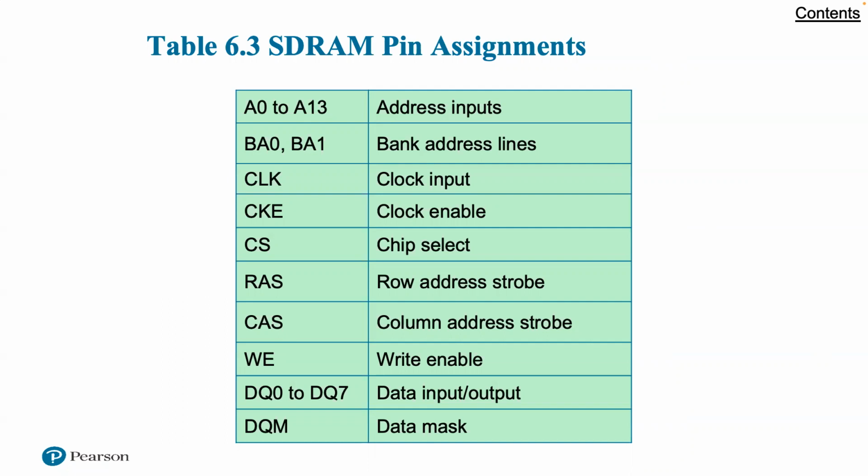The SDRAM employs a burst mode to eliminate the address setup time and row and column line precharge time after the first access. In burst mode, a series of data bits can be clocked out rapidly after the first bit has been accessed. This mode is used when all the bits to be accessed are in sequence in the same row of the array as the initial access.